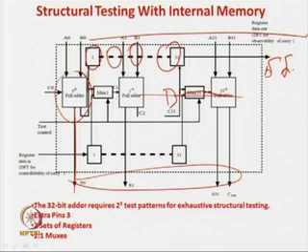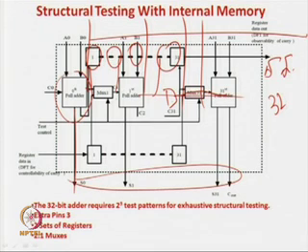In this case you require 32 clock pulses to get the result, because we are not bringing the carry outputs out in parallel; rather, we are feeding this carry to these units of shift registers. Once the testing is done, the shift register will be loaded with this value, and in a single go you cannot have the result; we have to shift out the result in a sequential manner.